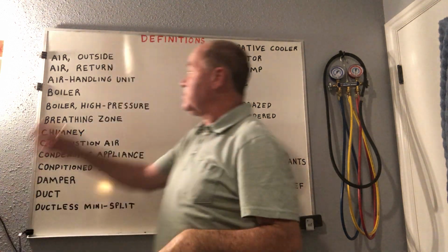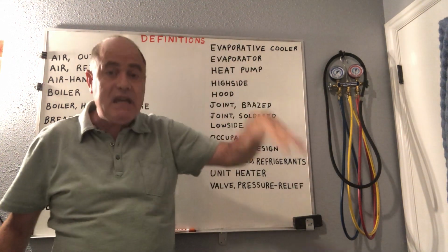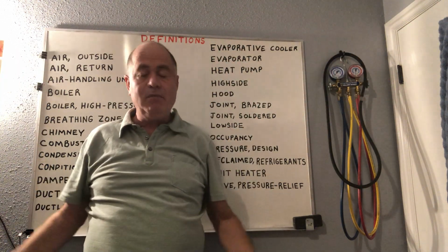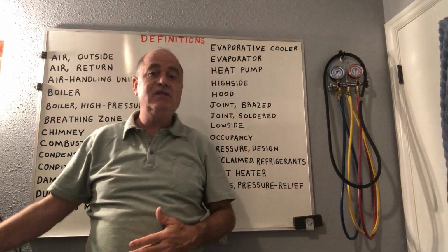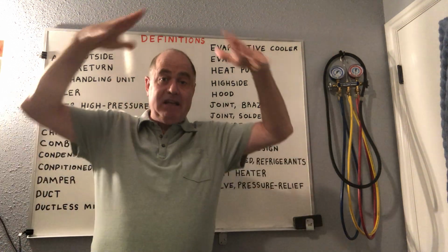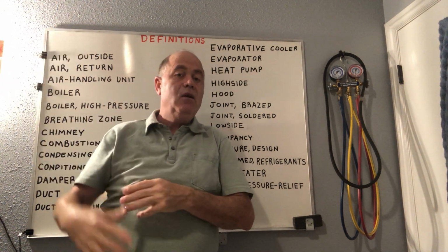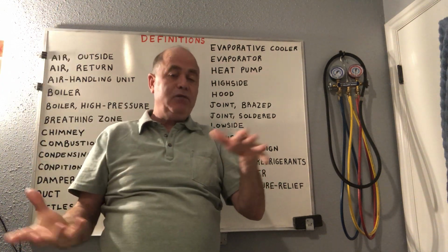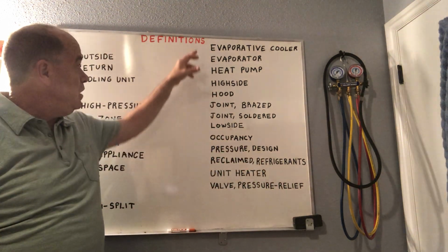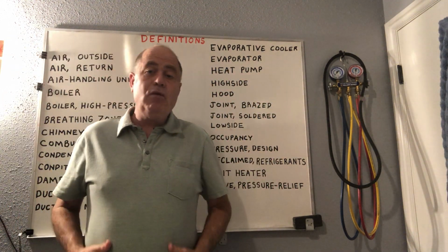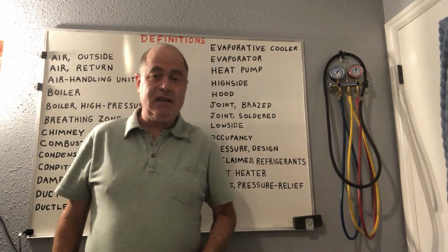Okay? And a lot of times we do also use this in restaurants just to make up air, right? Kind of like outside air, make up air, to bring in air for all the air that's being lost because we have so many exhaust fans in the bathrooms and in the kitchen and those big kitchen hoods. We have a lot of air leaving, and if air is leaving, we need to balance the air, and we generally bring that in through an evaporative cooler.